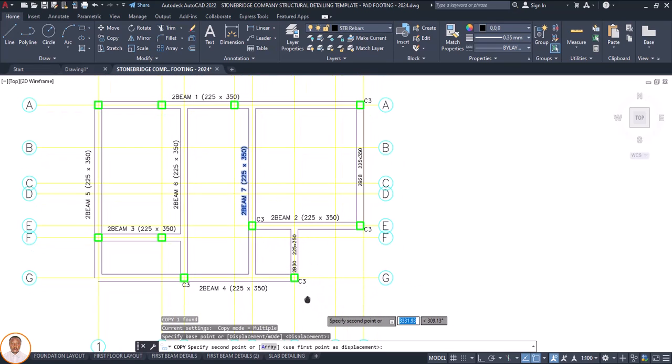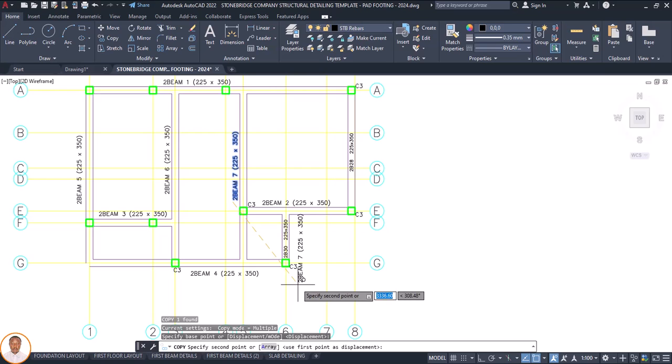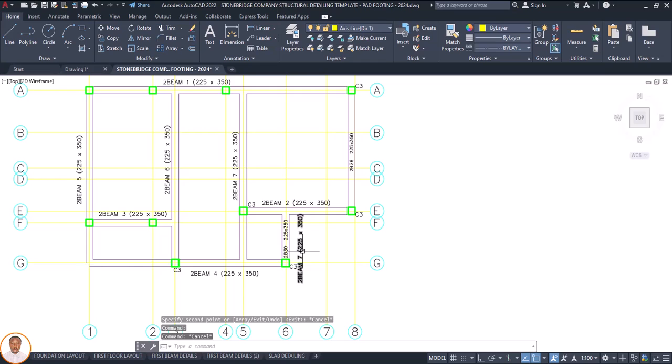It's on this, second to the last. Is that okay? It's on this. So if I like, I'll click on it. Understand? Sorry. I'll click on this to reduce it. Then there's SC, which stands for scale. Enter. So at this edge here, 0.7. Enter. So you can see, I can reduce it. Is that okay? So enter.